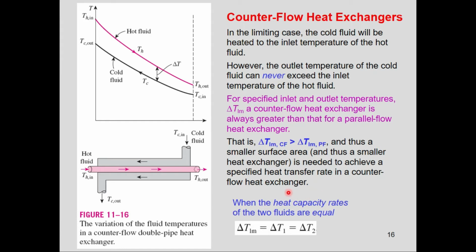One thing that you need to keep in mind as well is that when the two heat capacity rates of the two fluids are equal, the log mean temperature difference, the delta T1 at the inlet and the delta T2 at the outlet are all the same.